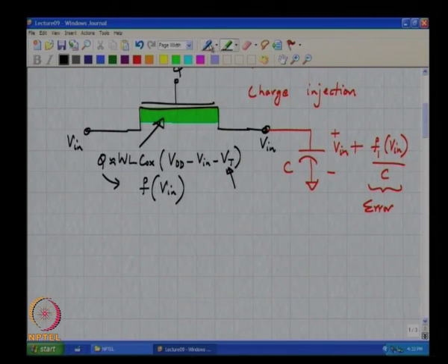As I said, in electronic system design often gain or offset errors are benign errors, in the sense that an offset can of course be corrected given it is constant from cycle to cycle. Gain error is often acceptable because it is a linear phenomenon.